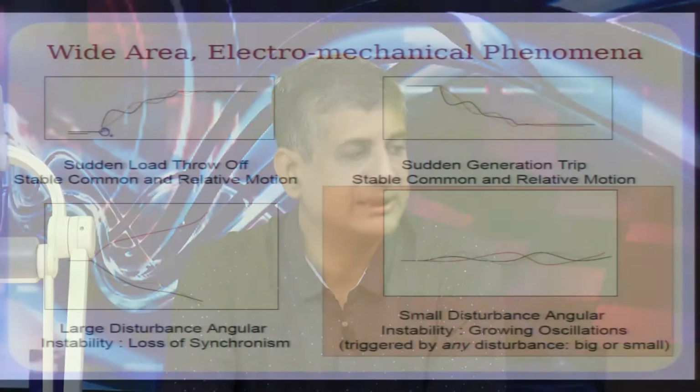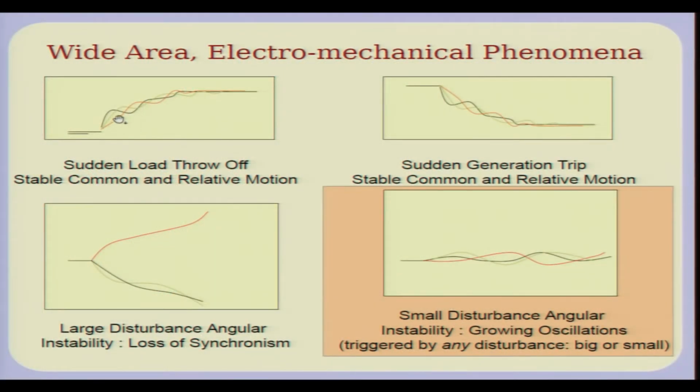That is, the total load should be equal to the total generation, of course, and also the generation to account for the losses which take place in the system. Once that equilibrium is reached, if it is reached at a certain frequency, the system will settle to that frequency. So, if you are already operating at a given frequency and there is a load tripping, then the generator speeds will go to a new equilibrium depending on how the governors in the generating systems react.